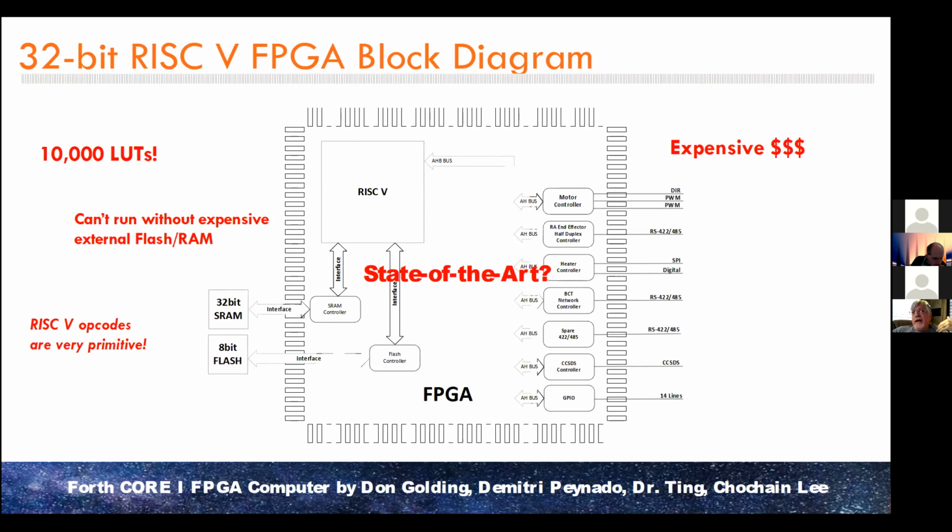Right now, we have the basic outer interpreter working with a single character word width. So it's not a string yet, but it is working, and it's 2,500 LUTs. So you could fit 4 of our Forth engines in the same amount of fabric space as a RISC-V.